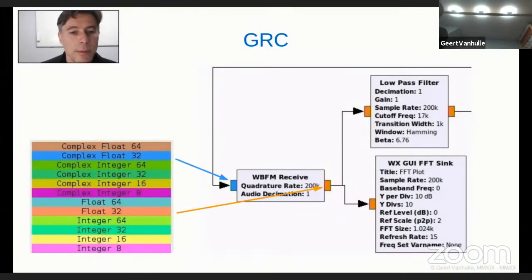The one we've been working with so far is a complex float of 32 bits, which is a complex number, a float of 32 bits plus j times another float of 32 bits. That's the complex float sample. And we have a whole set of other variable types available, and in my demodulator stage here we will go to a regular float of 32 bits.